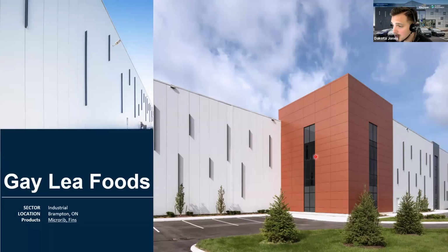But on the vertical circulation, we go with something way more architectural. This kind of nice orangey terracotta look. We're doing more of a flat panel. Still in IMP, of course, but we're doing that angled corner with these adjusted legs so that we can line in between this curtain wall and this corner. Again, no trim here, no seams, anything like that. Just nice intentional grid lines.